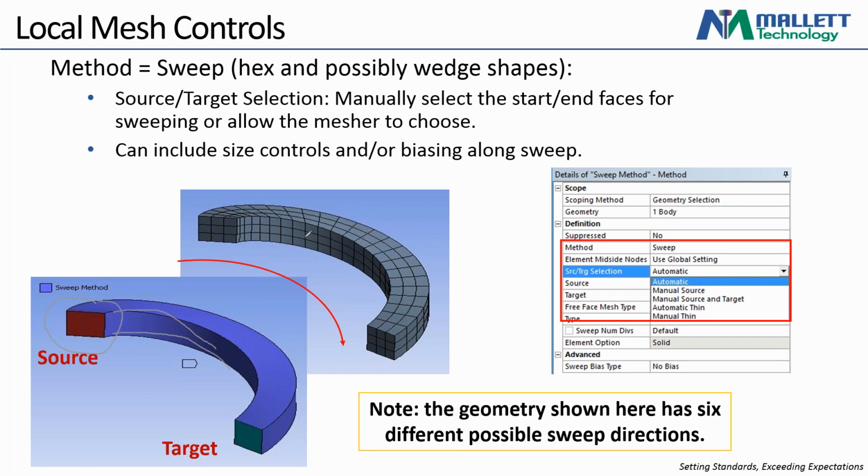It just projects it along the body, and then you get this mesh face cutting up the body along its entire length. This can be done really anywhere you see that continuous body occurring. So for instance, this part potentially can be meshed with a swept mesh six different ways. You can sweep it from top to bottom, bottom to top, along the arc like it showed before, or from the inside curve out or from the outside curve in. Any of them are acceptable.